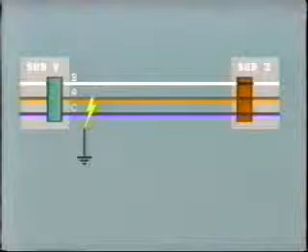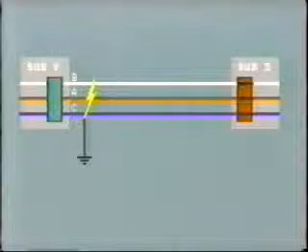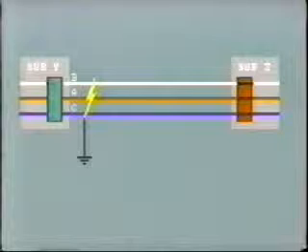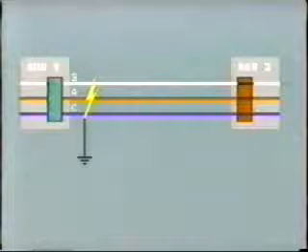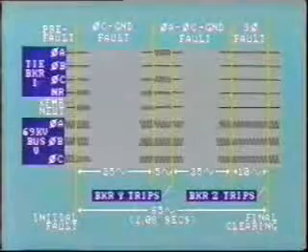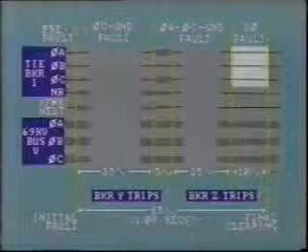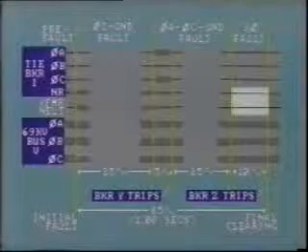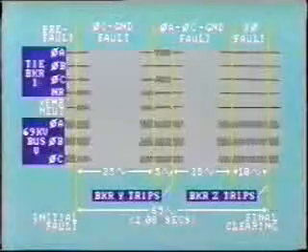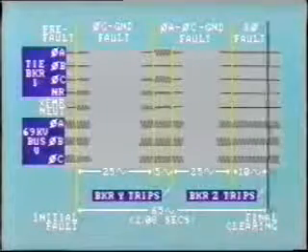At this point, the fault again changes. The A phase conductor now burns open. The tree contacts B phase and falls to the ground. But all three open conductors are now in contact with ground, resulting in a three-phase-to-ground fault. For the next 10 cycles, we have a balanced three-phase fault. You can see this from the three fault currents in the tiebreaker and the fact that neutral and residual currents are now zero. Breaker Z at the other end of the faulted line now trips to completely clear the fault.